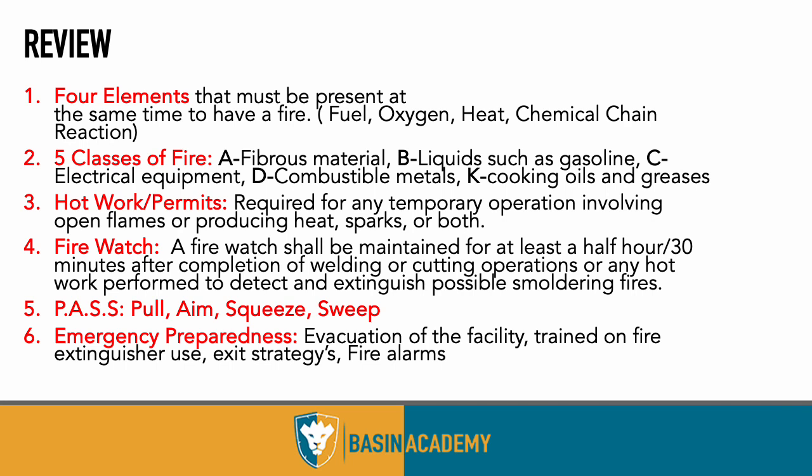So here's a slight review. The 4 elements that must be present at the same time to have a fire: fuel, oxygen, heat, and a chemical chain reaction. The 5 different classes of fire would be A, B, C, D, and K. Hot work permits are required for any temporary operation involving open flames or producing heat, sparks, or both. Firewatch: a firewatch shall be maintained for at least half an hour after completion of welding or cutting operations or any hot work performed, to detect and extinguish possible smoldering flames.